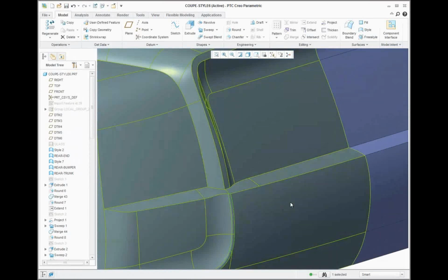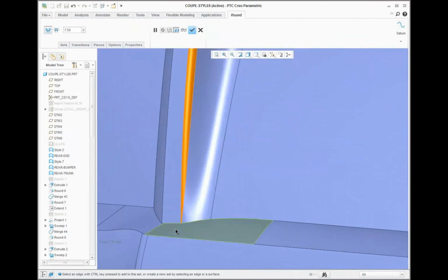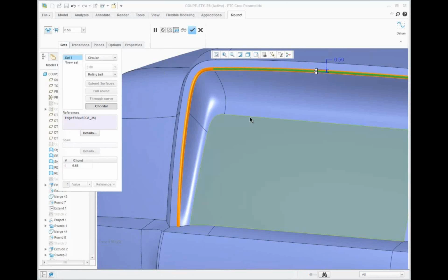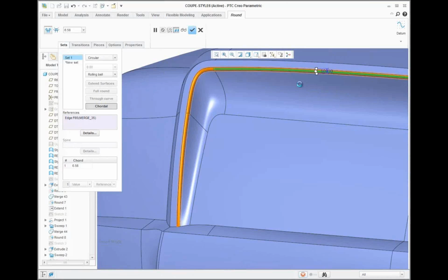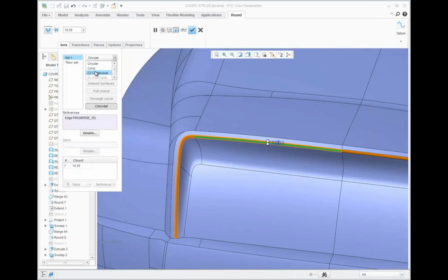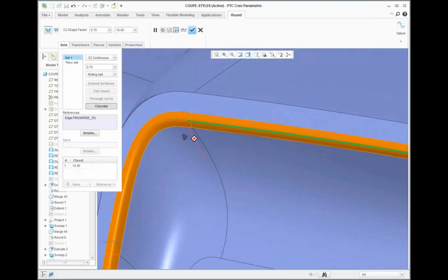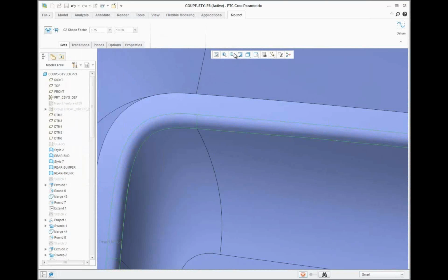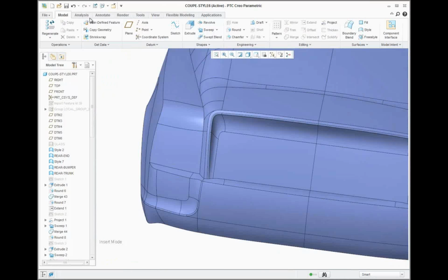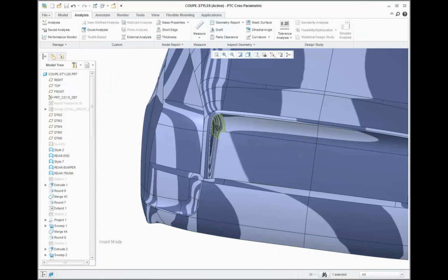We'll do this again, another edge. Again, you see how that round kind of tapers off near the end as the surfaces become more tangent. In this case, we apply the chordal round option and the resulting difference. We change it to curvature continuous. We have the options to edit the tangency. And this makes for a really clean surface transition. If we look at this with a reflective analysis, we can see how nicely that round gets created.